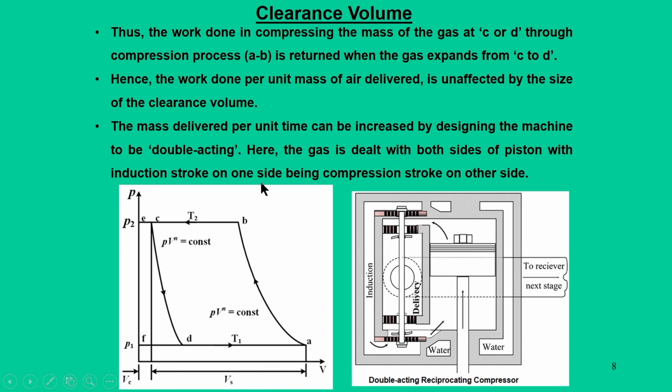So, the other way of looking at the same problem is that we can say it is single stage compression, but double acting. Double acting basically means that during the compression stroke, the other side would be an expansion and vice versa. So, if the induction and delivery valves are arranged in such a manner, when the piston compresses, this part of the gas gets compressed and the other part of the gas gets expanded, or it is a delivery.